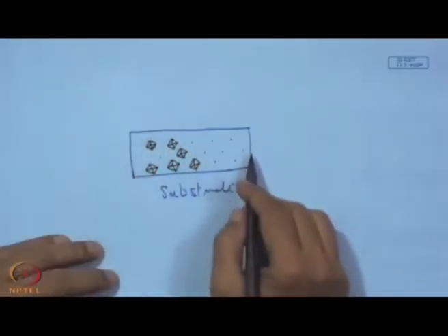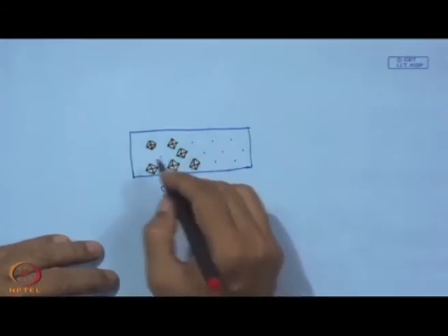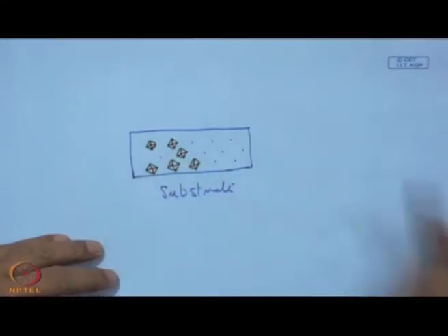From the chemistry point of view, it should be a carbide former, and it should have a very close matching thermal coefficient of expansion, the E value should not vary too much. If we can satisfy those things, then it will be another promising technology using this CVD process, not for getting a continuous coating, but a coating over the substrate surface with selective growth.